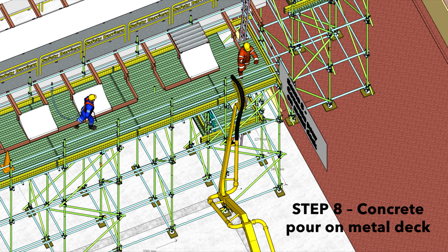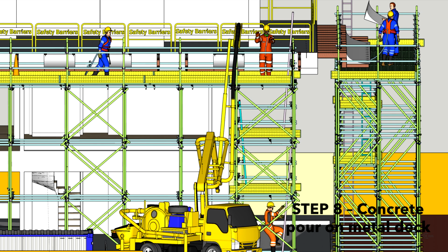Take note of the positioning of the workers and the equipment. The pump arm extends over the work area. How does this influence the planning of the pour? What safety checks must be in place to ensure the stability of the pump truck and the safety of the workers? Look at the staging area for the pour. Is there clear access for workers? How might the flow of concrete be managed to prevent overflow or excessive weight in one area? Reflect on the potential risks involved in this activity.